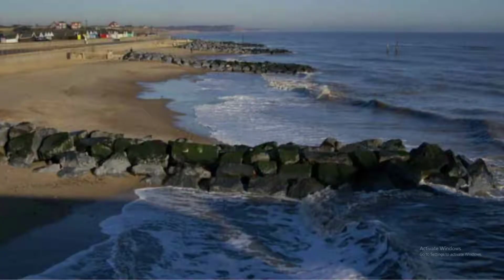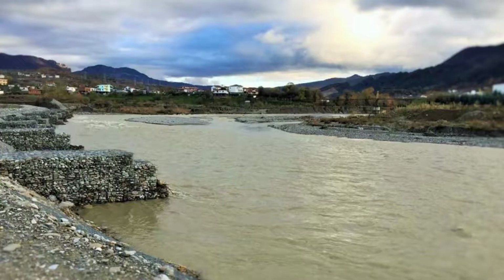Secondly is the material the groin is built of. Most groins are built of rock, timber, or gabions, with rock being the most common. Rock is a cheap material for construction with good durability and helps absorb wave energy. Timber and gabion groins, in contrast, last much shorter and tend to reflect wave energy rather than absorb. Concrete, steel, and other more expensive materials are also commonly used.